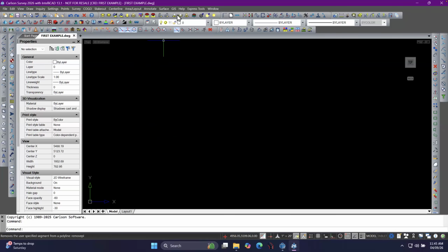All right. So now up here, for instance, on this polylines toolbar, there's a command. You see the picture is a little pencil eraser hovering over this dot on the end of this line and arc. That's a polyline. There's another one here that says remove a polyline segment. I used to have it color coded a little better. That used to be red on that segment with the eraser. So it's telling you you're either going to remove a point from a polyline or a segment from a polyline. So that's the remove polyline vertex. That's a command I use all the time.